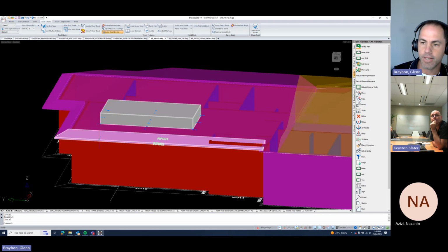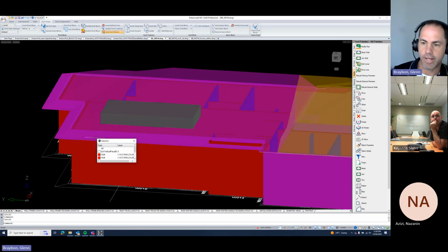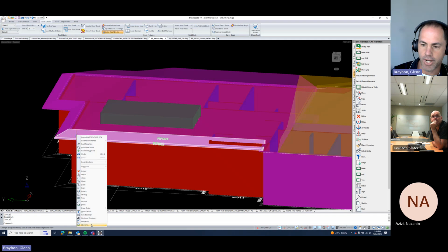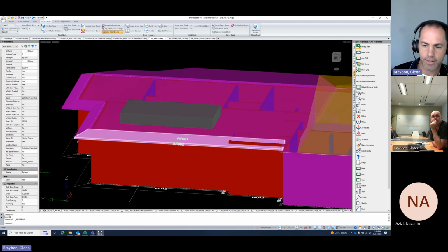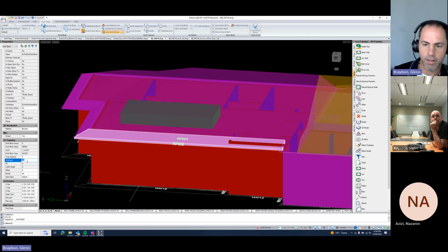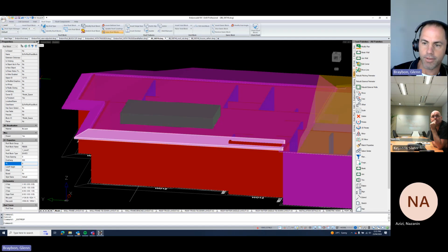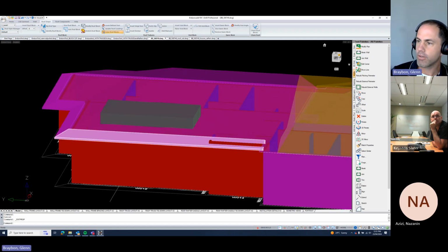While we're there, a similar kind of option with your eave overhang. If you want to adjust the overhang, we can see the overhang is 530. I'm gonna make it 600. Awesome. That's really cool. You adjust that in the properties menu there. Yeah, so that's probably one that I was going to show you.